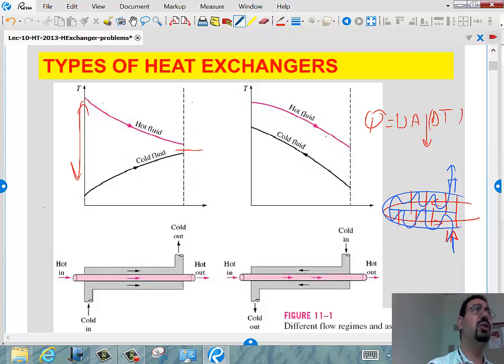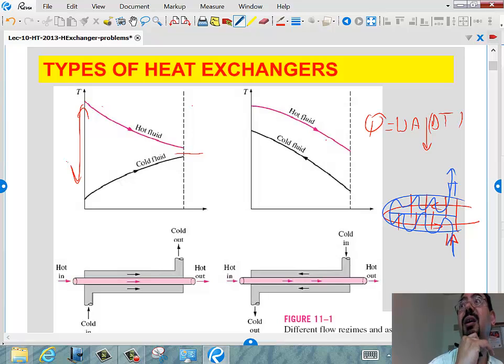Remember the regenerative cycle, all those feed water heaters you had in thermo 2? Why did they have all those? It's to send the water to the boiler at an already warm temperature rather than sending very cold water to the boiler. So you can see that parallel flow ends up setting a ceiling for our dreams. We cannot go that high, and it will result in very high irreversibility. It will make our cycle efficiency really bad.